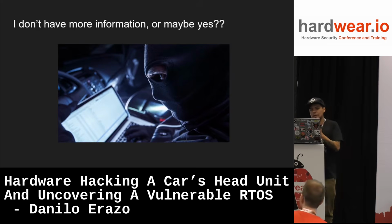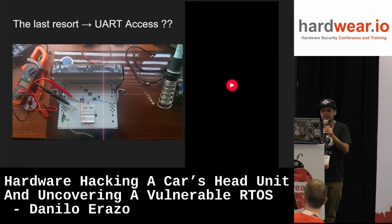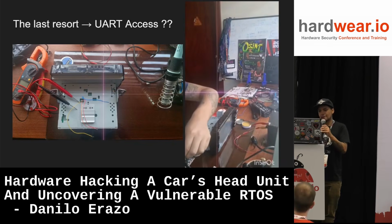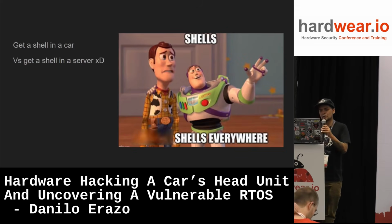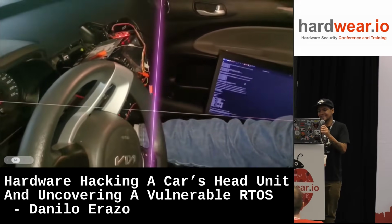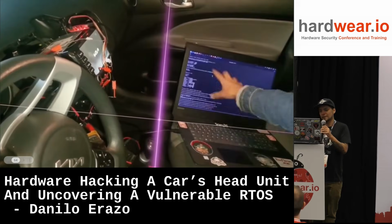Okay, I don't have more information on MRBS. I was able to discover a UART access on the backside of the head unit. So immediately I soldered the UART pins, and after that I got a shell in the car. Let's go to start. Here I am going to start. Right now I'm going to show all the boot process.